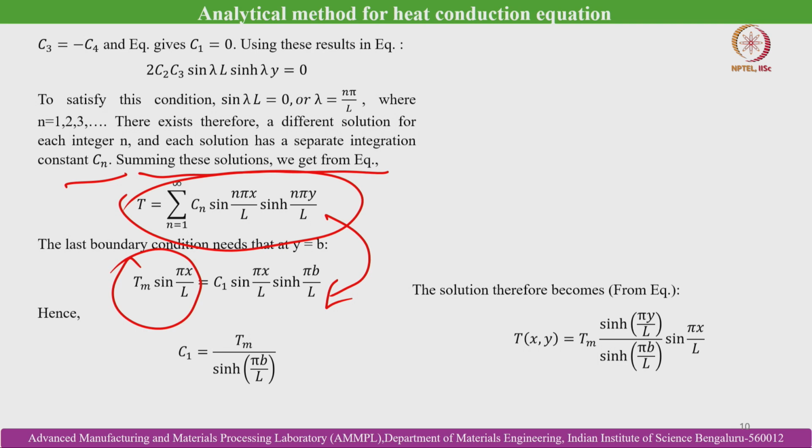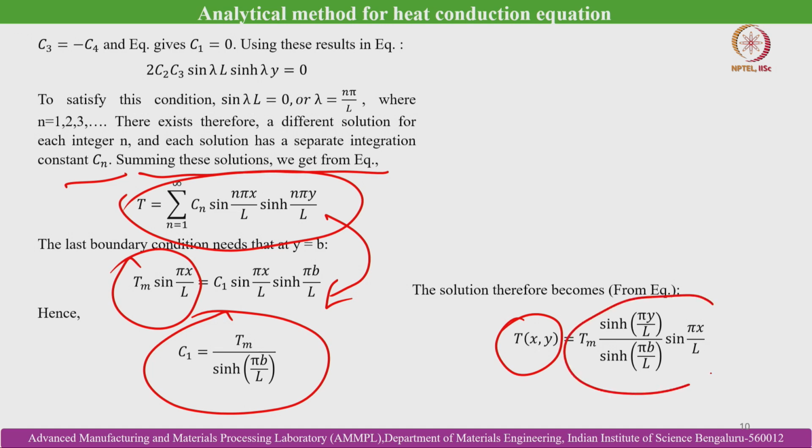So, from here we can evaluate the value of the constant C1. C1 becomes equal to Tm divided by sinh(πb/L). The solution therefore becomes T(x,y) equals Tm sinh(πy/L) divided by sinh(πb/L), into sin(πx/L). So, this is the analytical solution of the heat equation, that is, the Laplace equation.